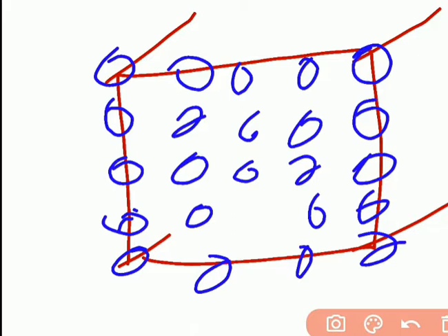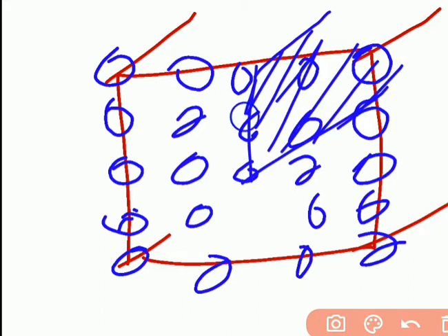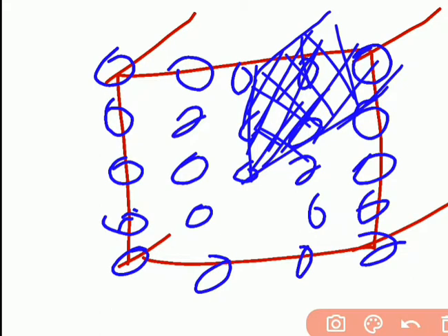So due to this missing plane of atoms, there is an attraction between these two atoms and they will come close. Okay, so what is dislocation line here? We need to understand dislocation line. Dislocation line is the line which connects all the atoms in the extra half plane at the end. So this is our extra half plane. You can see it going in the inward direction. It is the plane which is containing extra atoms, and dislocation line is the line which connects all the atoms in the extra half plane at the end.